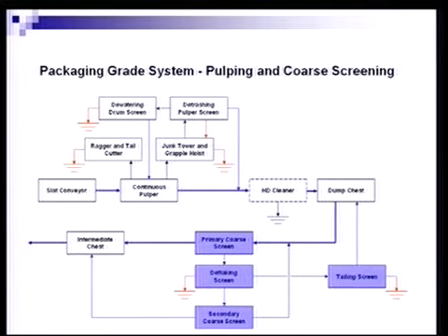There's a primary coarse screen whose function is to remove the flakes and the debris, concentrate that debris so that the deflaking screen, which is in the secondary position, has some material to work with. And in that position, we'll want to add some additional horsepower into the screen. We'll want to have a different type of screen so that we can do some fiber recovery by treating the